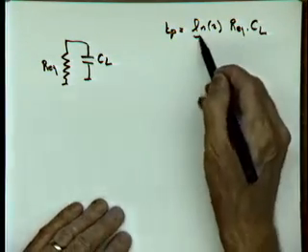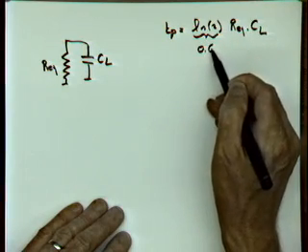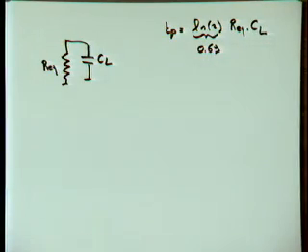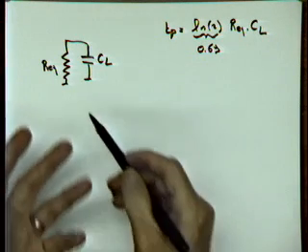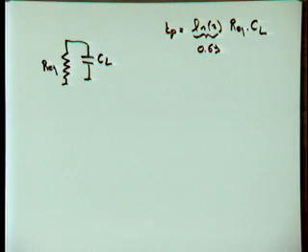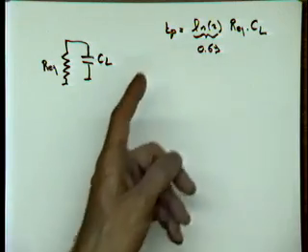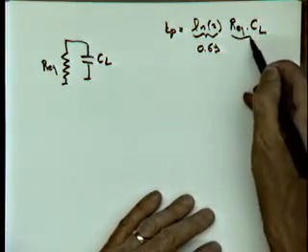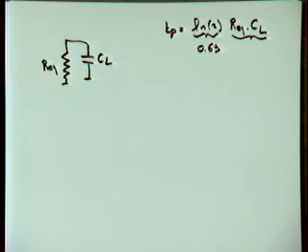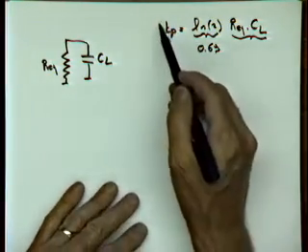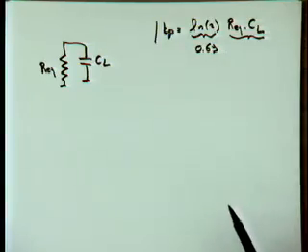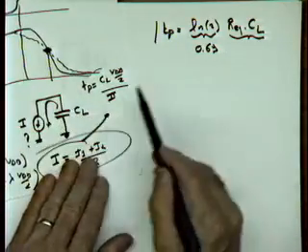And this ln2 is 0.69. That's a standard circuit. It's a first-order RC network. We know that the propagation delay of a standard RC network is the time constant of the network, R equivalent times CL, times 0.69. Okay? So that's easy to compute. The equation is a little bit easier than this one here.